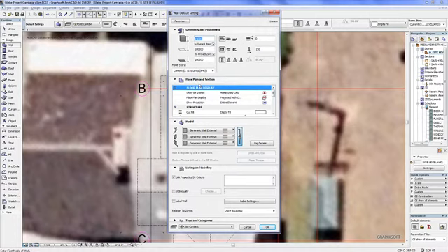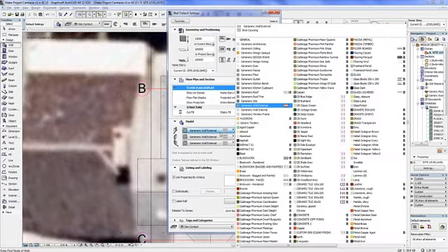made them very high, because the intention is to make the walls a height that is over and above the roof planes, so that we can trim off the excess of the walls that poke up over and above the roof planes. Now, we talked also briefly that this generic wall has this cover fill or vectorial hatch, which gives it this funny sort of weatherboard type cladding on the outside, which we don't actually want.